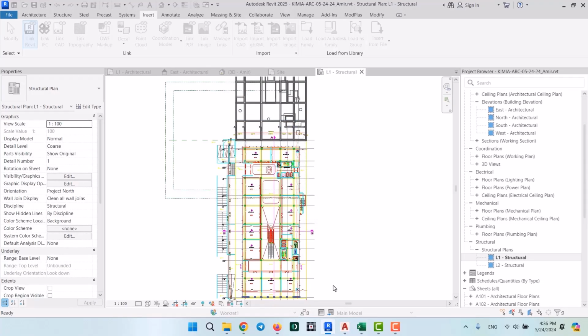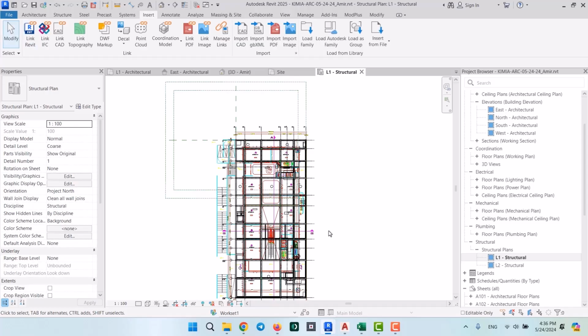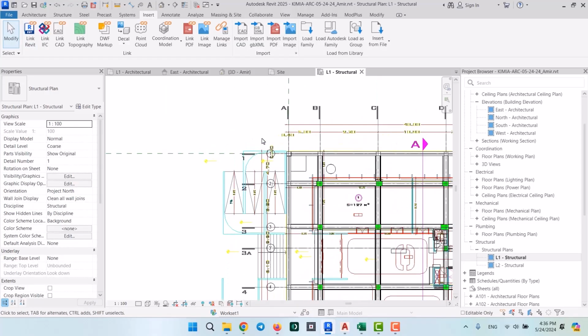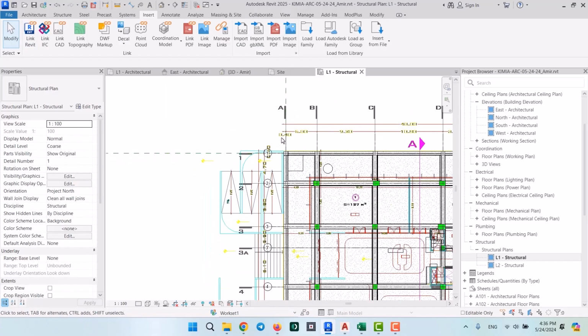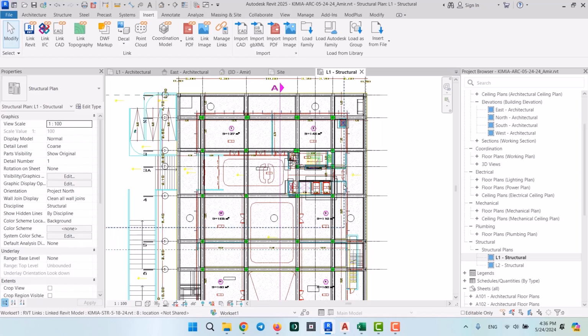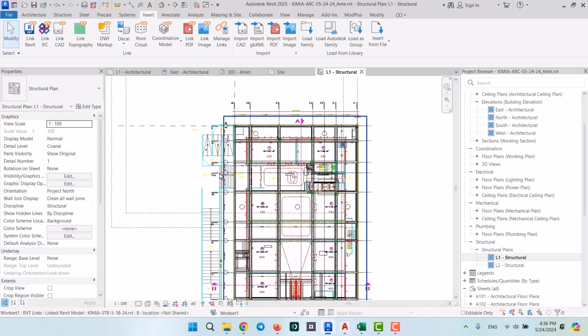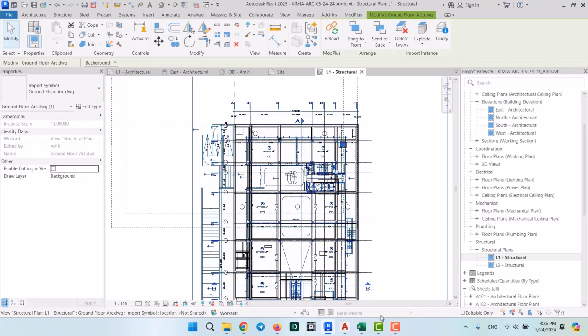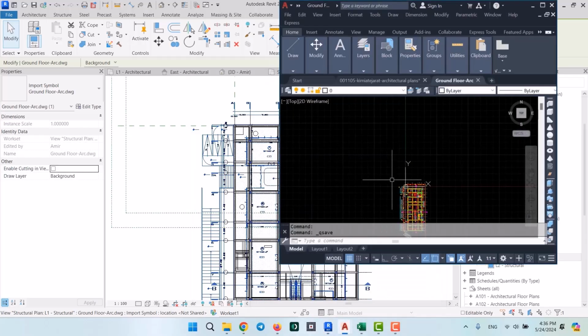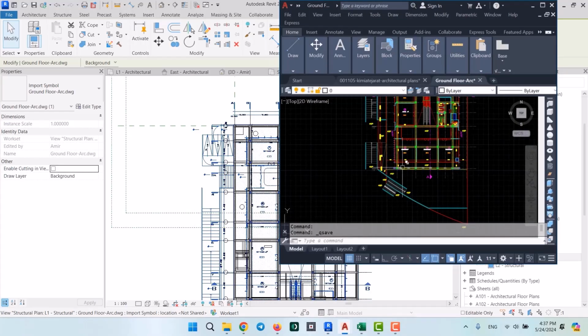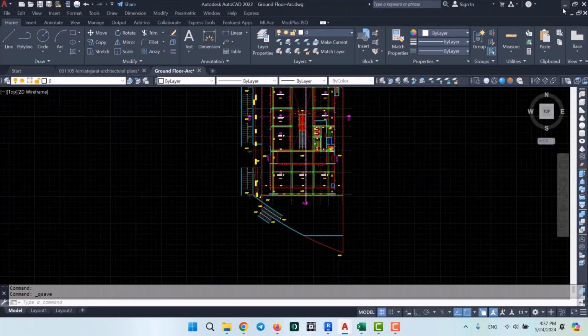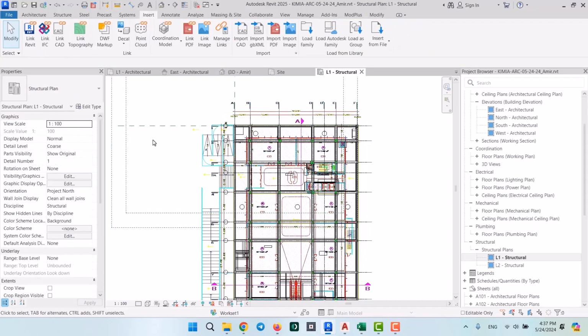This message isn't really that important. And so as you can see over here, once again the 0 points are aligned. So this is also another way of doing it. Or you could also go back to your main CAD file, then change the 0 point to the intersection of 12 and 1, or wherever else. So those were the two ways of aligning the 0 points. Now we're going to move on to save time.